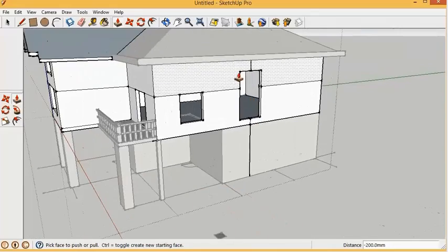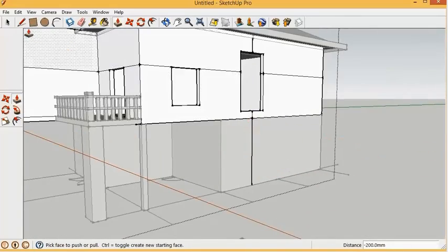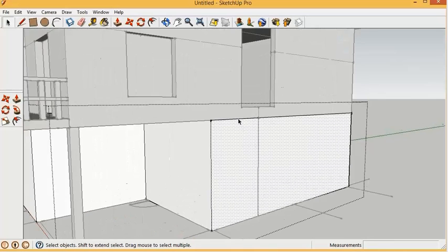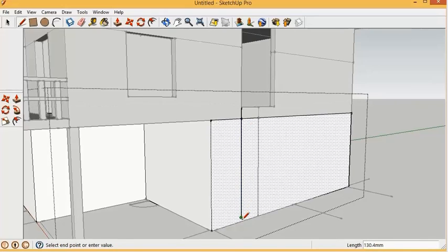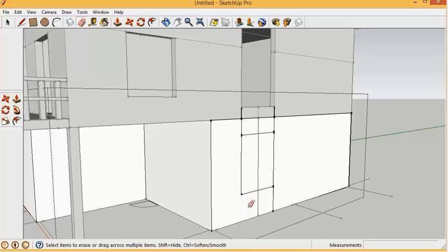Let's go ahead and do one more. We're going to do 3D text. And this time let's just do it filled. And again, let's just type in the same text. Press place. You can see now it's created faces on top of those outlines. So now we have filled text, but it's just flat. So it's not extruded. And so let's just see what extruded looks like. I'm going to turn on extruded. And when that's turned on, it lights up this window here. So let's go ahead and type in the text.